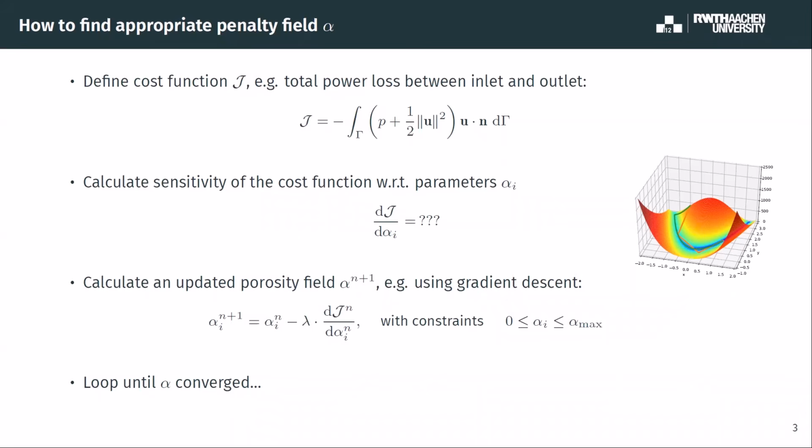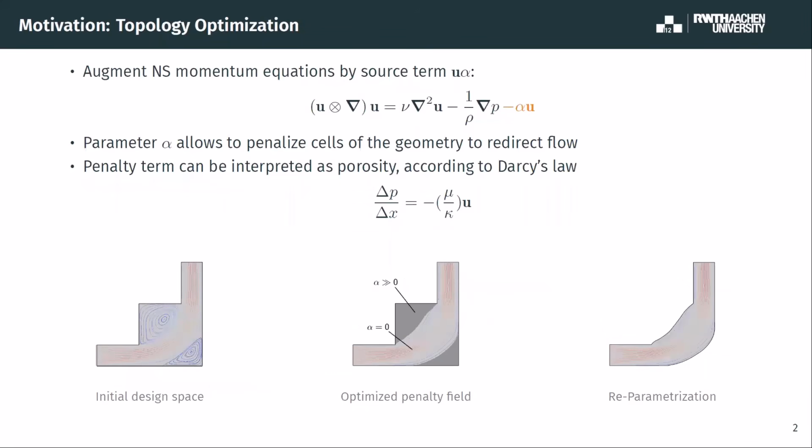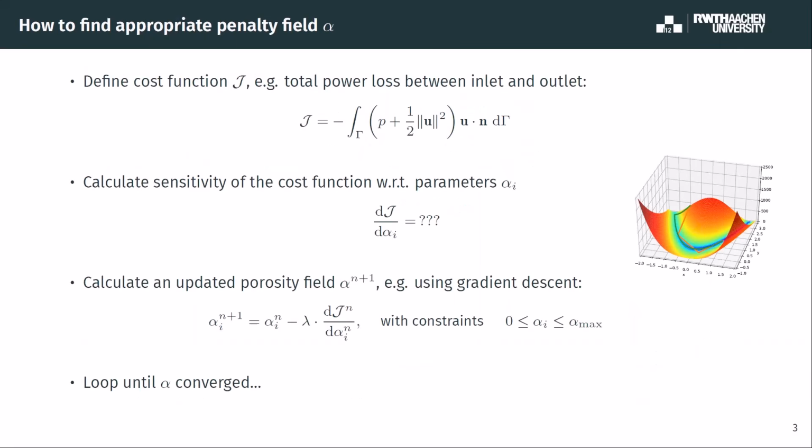And also you have to constrain the parameters in order to make it physically meaningful, so that in this example, we just don't introduce a fan into this, which actually pushes the flow along. So we want to be able to penalize it, but we don't want to give it a boost, so to speak. So we introduce a clamp on these parameters.